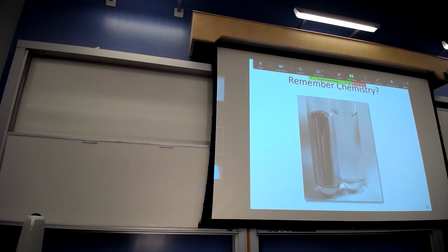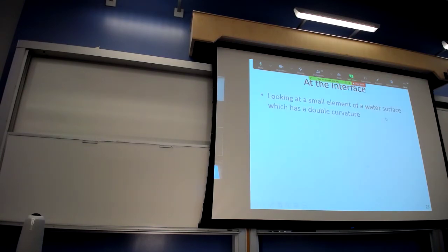So again, the aspect we're looking at is we're going to take a little coupon, a little differential piece out of the surface on the right. And we're going to do an analysis on it. Why is that deflecting the way it is? Well, you have a finite volume of the water, and it's deflecting because you have two immiscible fluids, air and water, and a finite volume of one. So surface tension manifests itself by deflecting the surface into this meniscus. And I know you've all seen this.